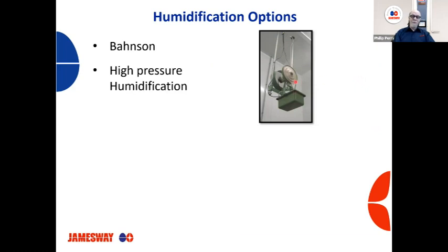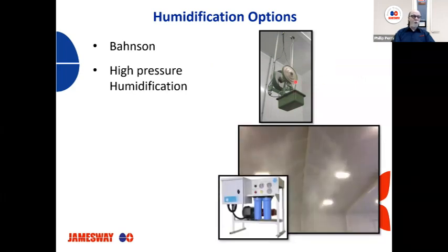A lot of hatcheries are going to a more high pressure system. It's 1200 PSI, and it provides a much finer mist. You don't have any floor wetting as long as it has ample ceiling height, no wet spots on the floor. It's a very good, very reliable system, and a lot of hatcheries are moving to this, both in multi-stage and in single stage.